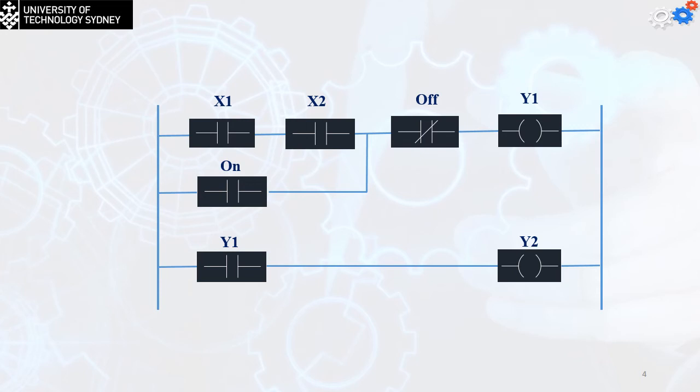For the robotic arm, simply, we are going to add the waiting time on each machine for the second part, subtract it from the waiting cycle time, and this will give us the utilization time for the robotic arm. By dividing this time by the cycle time, we are going to have the utilization percentage.